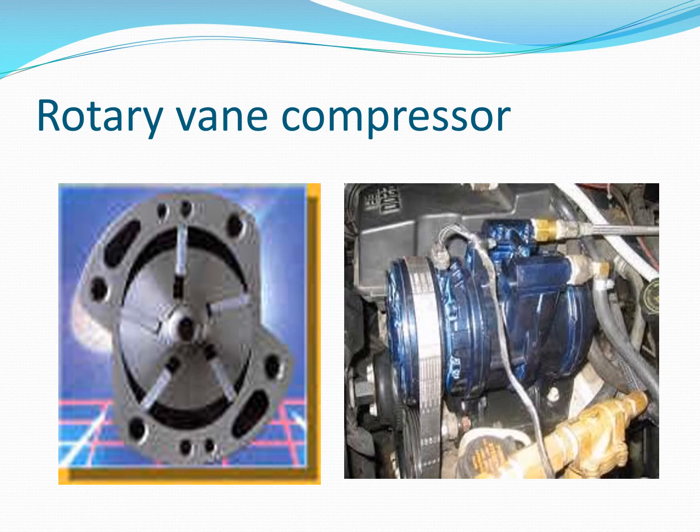Rotary vane compressor. This is very much like what's inside of your air impact guns they're using to remove and install bolts and nuts. The inside consists of a drum with these vanes, and as that drum rotates, the vane has a spring behind it that's springing it out against the housing.